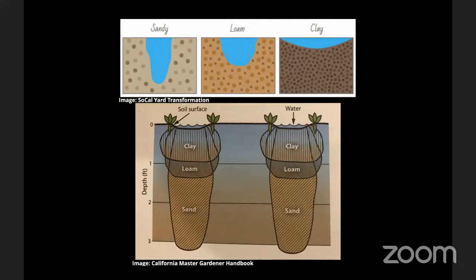But then understanding and dialing in how long to water for becomes a bit of a mess. So physically, can you do it? Yes, but it becomes a little bit more complicated. If you're working with button emitters, you're going to be calculating it differently. You're going to be figuring out gallons you're delivering to each plant, not how you're delivering water to the whole root zone. And again, for that, I'd go to the link to that guide that I posted in the chat.